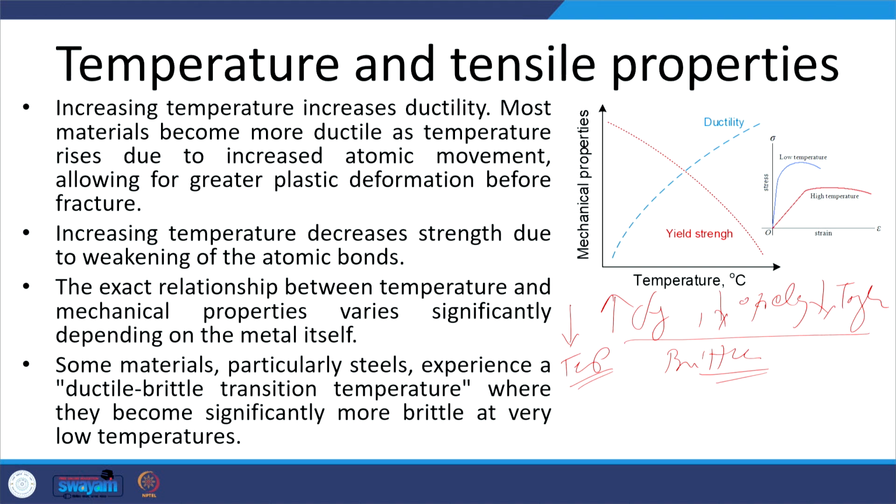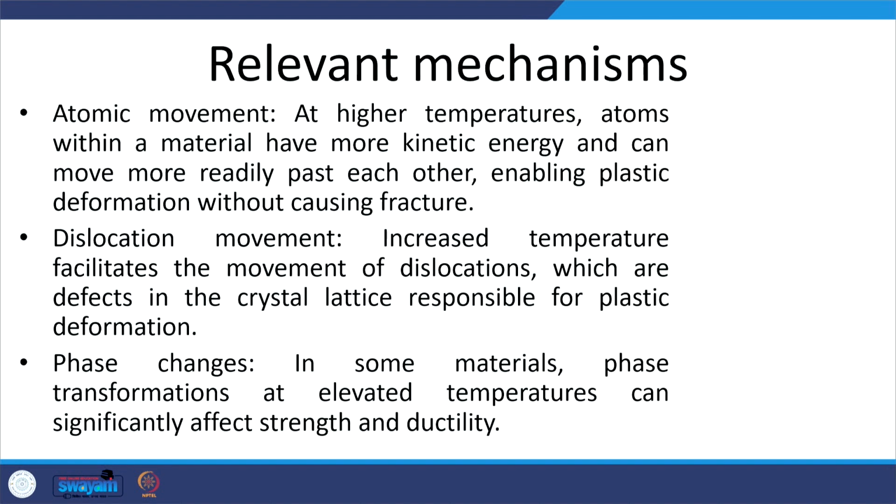At the same time, the work hardening tendency at a higher temperature is also minimized due to the continuous recovery and recrystallization that happen at a high temperature during the deformation itself. That also facilitates significant plastic deformation of the metals without cracking tendency at a higher temperature.